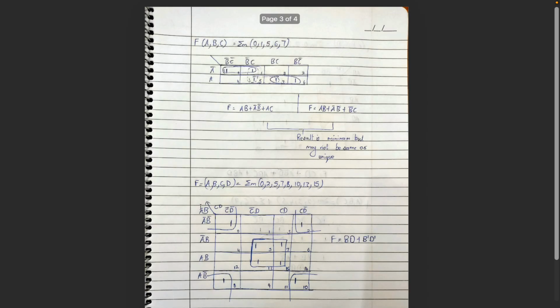There is also one more thing that I wanted to tell. Here, if you get a capital M, you will be marking all the zeros. It will just be the opposite of it. Solving remains the same. Only the way you write the numberings, you will put a zero and you'll solve it. And in that, you will not get sum of products, you'll be getting product of sums, POS. That is how you'll be solving. If I can, I'll make a video on that also.